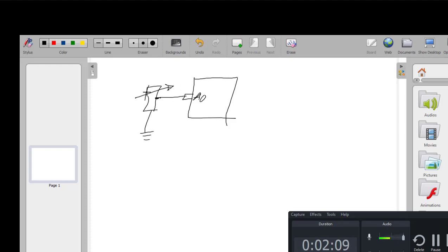So it is that digital value that we want to use in our pulse width modulation to be able to produce the different duty cycles on a port. In this case, we're going to choose digital port 3. So on digital port 3, we're going to connect our LED.